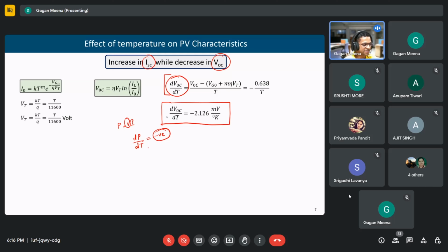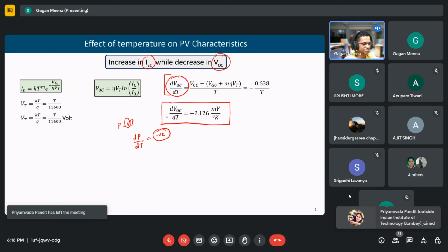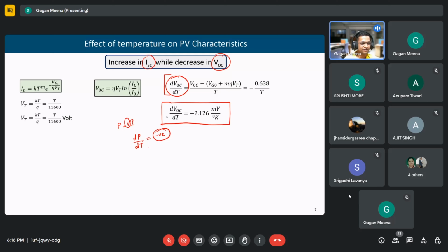Shadowing creates a lot of problems. It reduces the output of the overall solar system, and it also creates hotspots because there is imbalance. Somewhere temperature is more, somewhere it's less. So it creates localized heating, a hotspot, and that reduces the life of the solar panels. So at any location where we want to construct a new solar farm, a detailed analysis has to be carried out before doing that. That includes a shadowing analysis also.